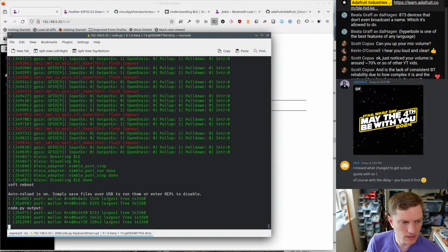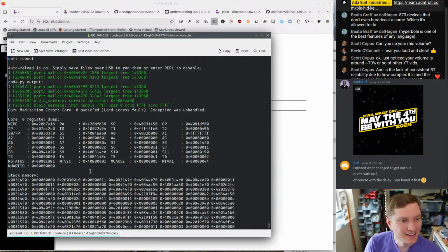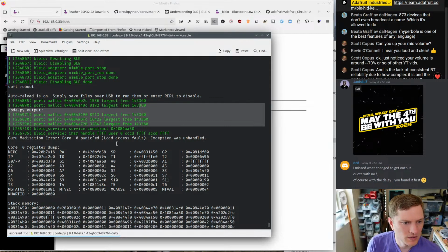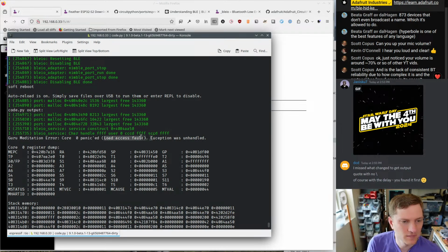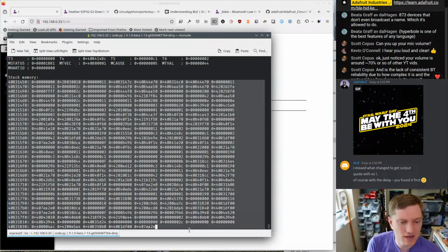So let's just do that again. Oh, and look at that. I crashed hard. Okay, so the second time around, we had plenty of memory, but now we've crashed. We had a load access fault. And so this is on a C6, and this is something I've been thinking I need to figure out, is it doesn't dump your stack frames, it dumps your entire stack.